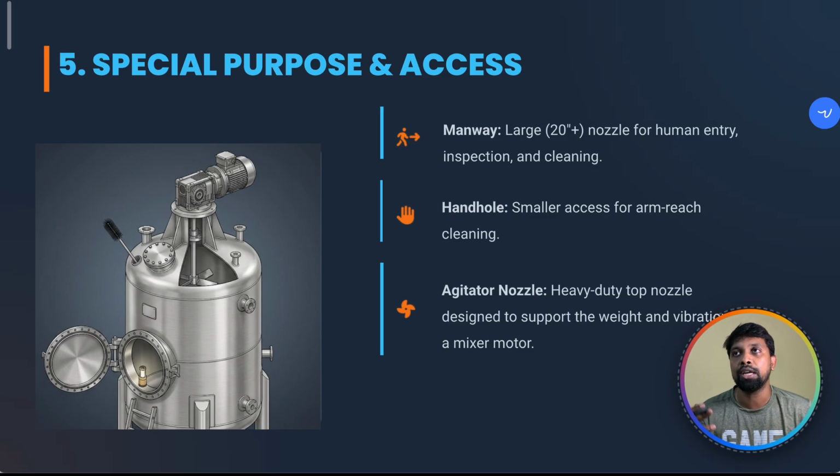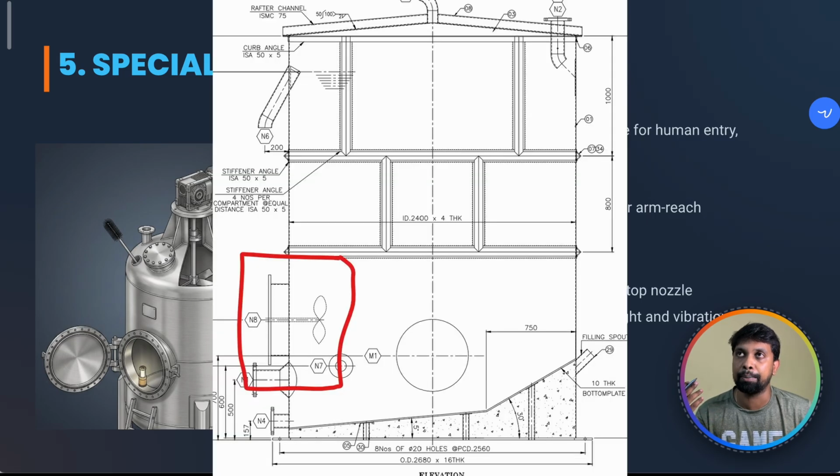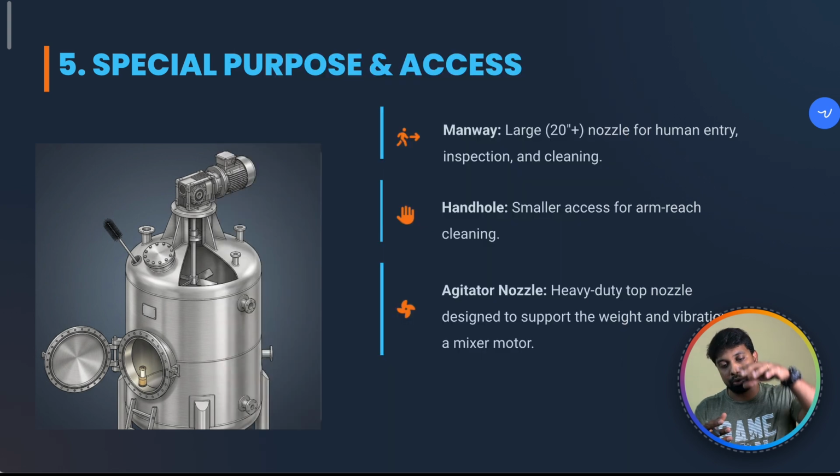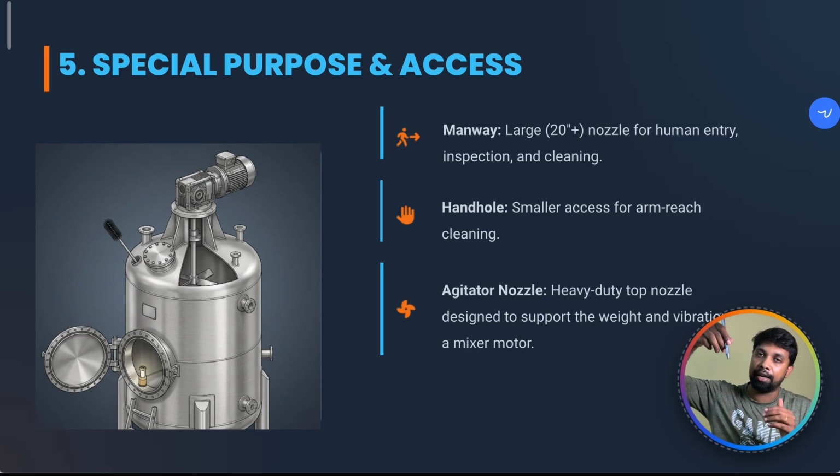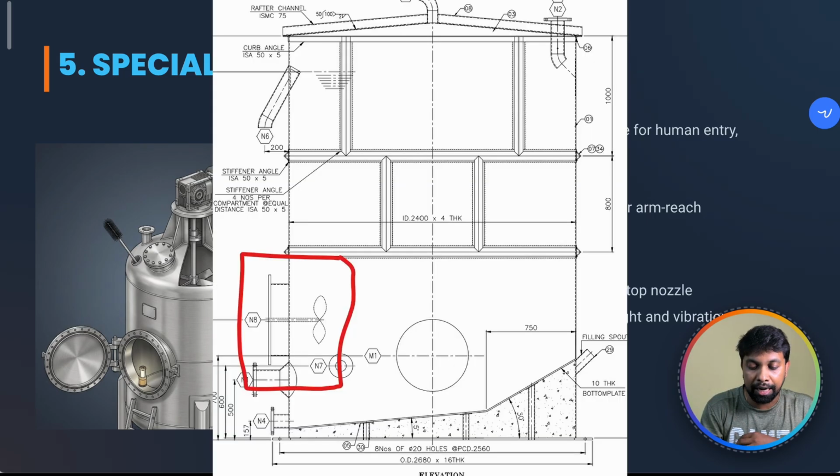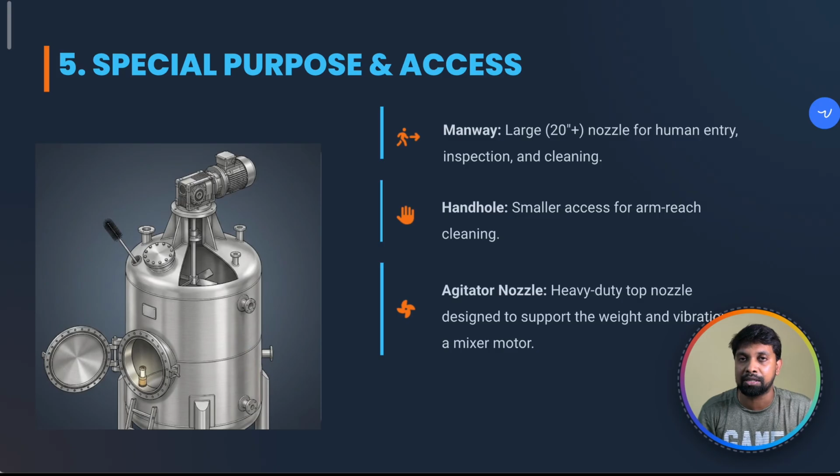You can see those kinds of agitators in a paper manufacturing plant. Paper has higher density, so it will settle at the bottom of the pressure vessel, and the vessel will be very huge in size. If we operate the agitator from the top, we require a huge amount of power, and the mixing is also not that efficient. For that purpose they will provide agitators over here. It is not most common in pressure vessels, but it is most common in storage tanks.